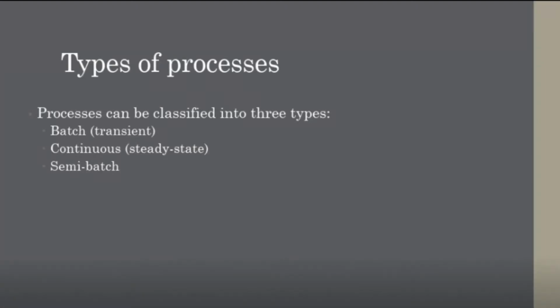For the continuous processes in which there is no chemical reaction, we can remove the terms of generation, accumulation, and consumption in our general material balance. Therefore, for a continuous process, we can simplify that by writing in is equal to out. This is our primary equation that we will be applying to almost all of our examples. Basically, when you say that a process is steady state and there is no chemical reaction, then you can use this very simple mass balance.